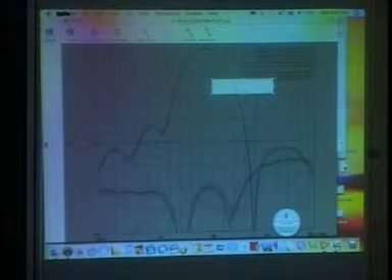Otherwise, in the movement, it was touching some area, and they cannot move that element out. So it was necessary for us to do that cut, and once you do that, we want to make sure that everything is fine. We know that if you cut a little bit towards the edge of the antenna, the effect will not be much, because the illumination towards the edge from the feed is less. So there won't be any difficulty. That's why we made a measurement and it was very nice.